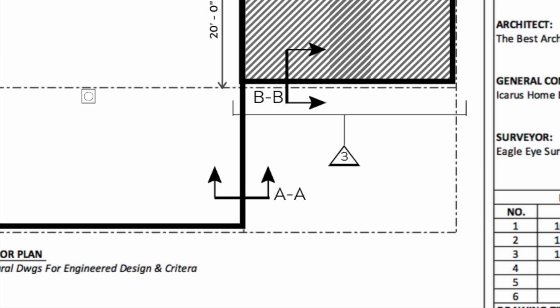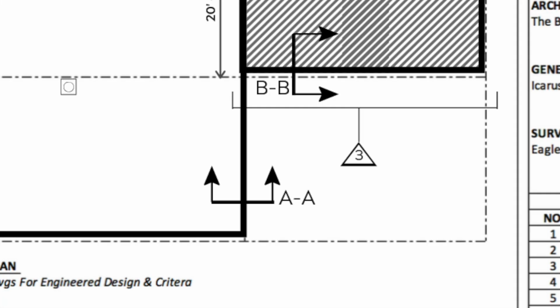Now you might be wondering, what are these strange marks labeled AA and BB? Well, like we spoke about with the slice of cake, these are known as section cuts. These marks depict where a section cut detail is taken. And as the old saying goes, the devil is in the details. Construction drawings are certainly no different. A detail is exactly what it sounds like: a portion of the drawing that provides more detail and additional information that simply can't be seen looking from afar.